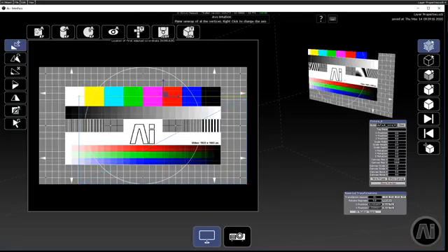You can apply this on planar, cylindrical, spherical modes, so they're really useful for different types of shape. Again, you can change the base axes that these are applied on by right clicking on them. So when I right click, you can see the letters there, so we've got XY on the sphere, right click gives me ZX, right click gives me YZ, and right click takes me back to XY.